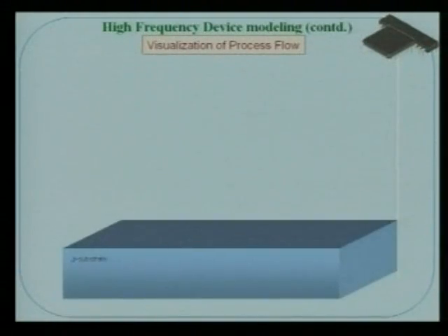Now going to the sample stage, what are the basic stages of CMOS? You start essentially with a substrate, which may be P or N type. What is the dimension of that? Normally we use 4-inch, 8-inch, 12-inch or 16-inch wafers. A wafer is a circular disc, and the thickness is 270 micron, 640 micron, 570 micron, or even 200 micron.